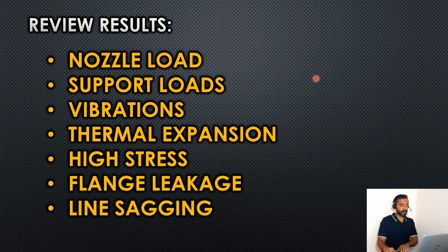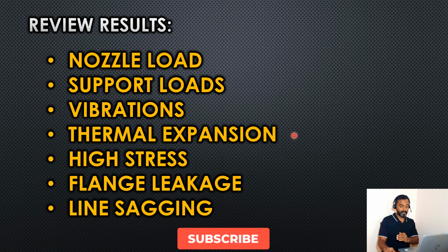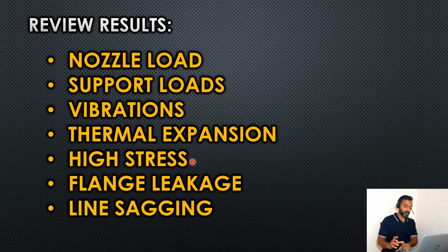So likewise, you have to plan various things like vibrations and thermal expansions. You can restrict the thermal expansion so that the line will not hit the nearby line. So you can see whether any part of the piping has high stress or not. So you will improve the flexibility of the piping in such a way that you can minimize the stresses.